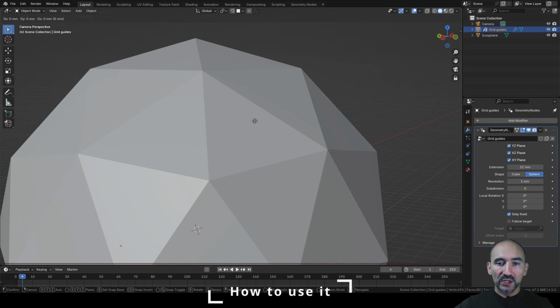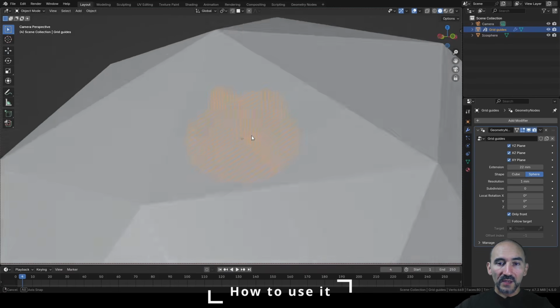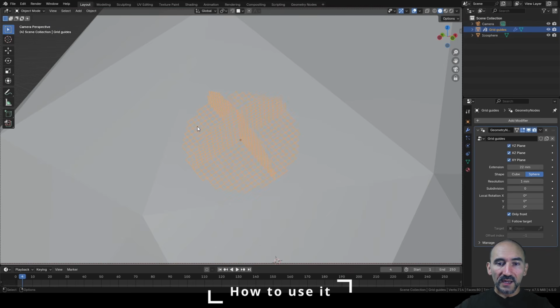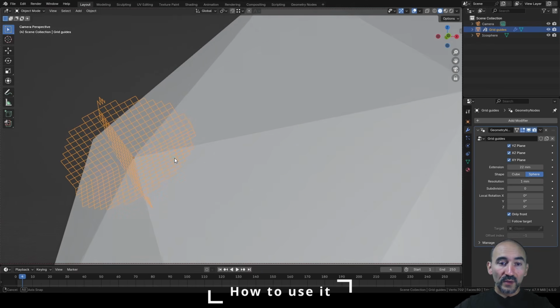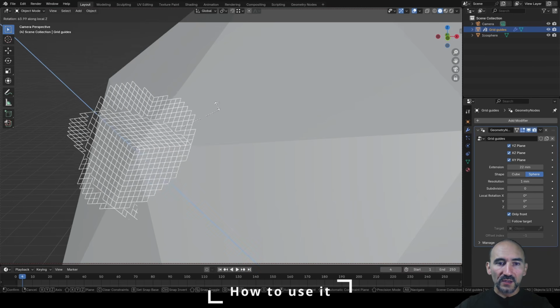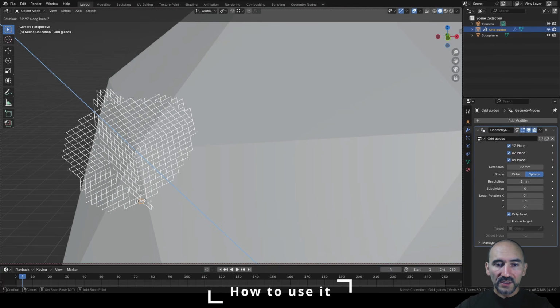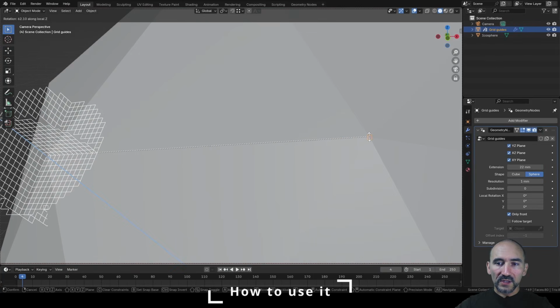We can press G to move and enable the snapping tool with the Control button and click on this face, and you can see this snapping feature. Now we can disable this align and set the snapping on the vertex and move this on this vertex. We can rotate these planes using the rotate tool with R and Z to enable the snapping on the Z axis, but not the global, the local Z axis. And you can see, repeating the pressing of the Z, this is the local Z axis, and pressing B to take one vertex from this grid, pointing here, for example, on this vertex.